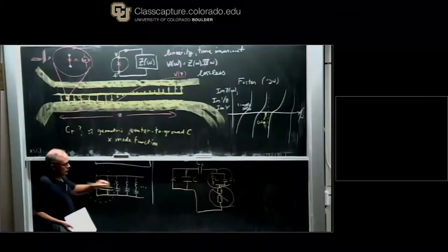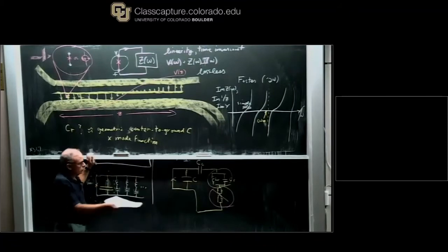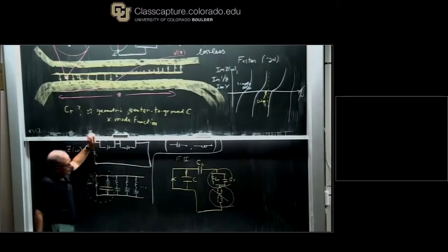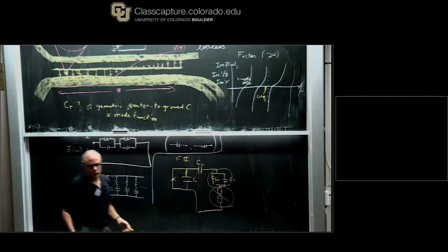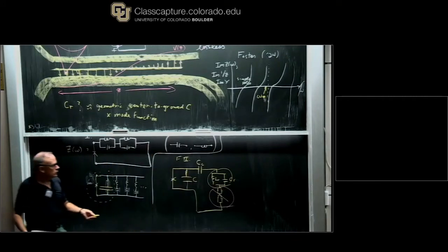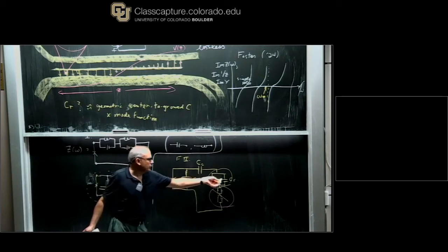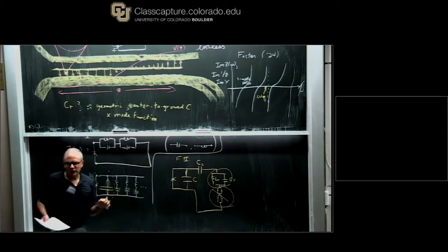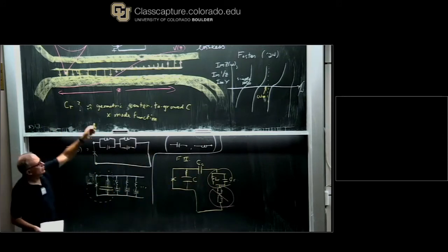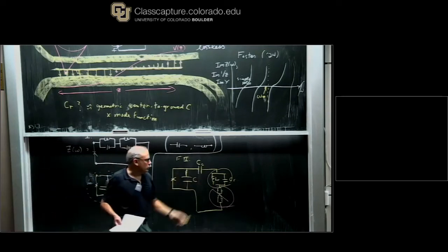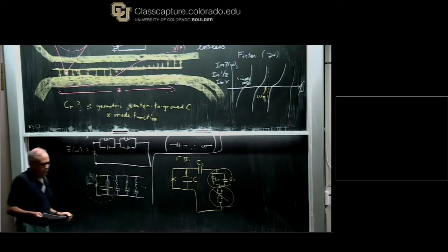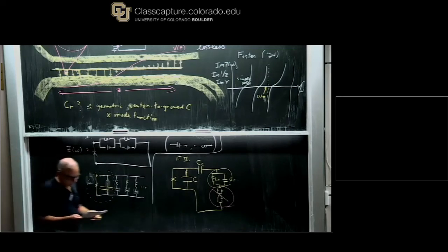What it is really is this. It's really do the electromagnetics, do the Foster theorem, do this fit, and then to very good approximation you've got what you should really call C sub r, and then also L sub r. The product is the less ambiguous thing because you know that this resonator has a certain frequency, and that's got to be given by 1 over the square root of L sub r times C sub r.